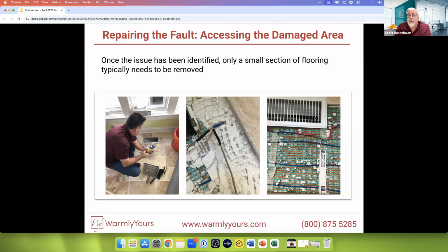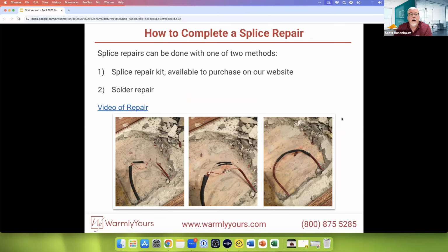And we had to replace that section there because the wire was damaged, because the plan they gave us didn't indicate where that was, and they were stuck. What happens when you take these areas and you put air vents or tubs or stuff like that, you're actually removing the heatable area of the floor. You're reducing the square footage that's available for the heat. Well, you start doing that, you're going to start running out of space. And that's what they did here. So perfect example of what goes on there.